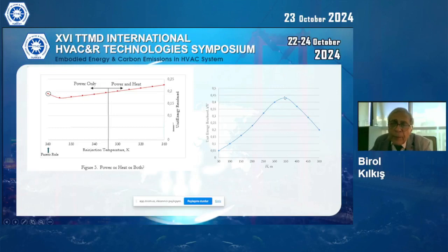So it proves that the reinjection temperatures must be as low as possible, down to the limit where you can get maximum power from the geothermal well, at a reinjection temperature of about 340, and by coincidence it also corresponds, in this specific case, to 360 meters, not more. A shallow well or a much deeper well may render a high temperature, but due to the embodiments, the optimum is somewhere in between, about 360 meters, not more, not less.